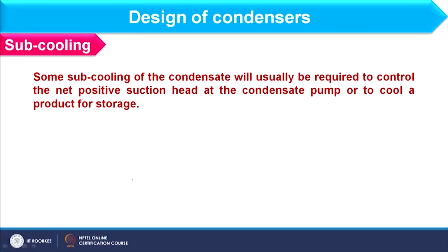As far as subcooling is concerned, some subcooling of the condensate will usually be required to control net positive suction head at the condensate pump or to cool down the product for storage. Okay.